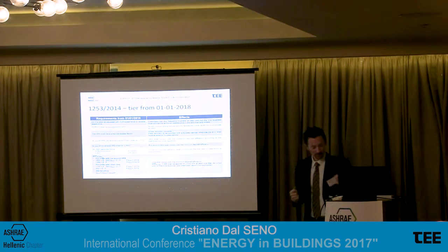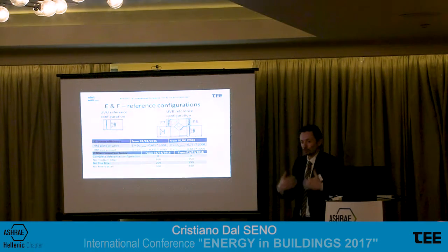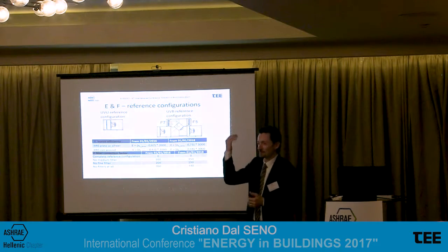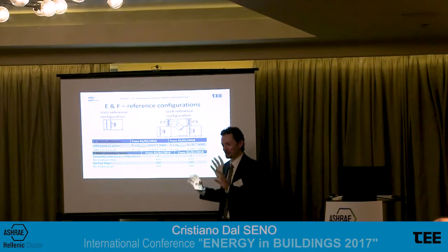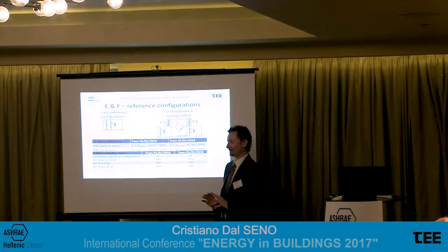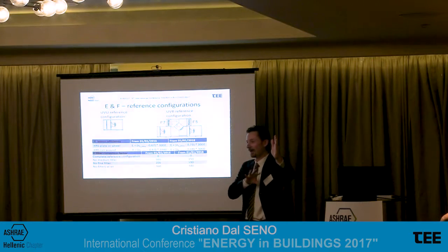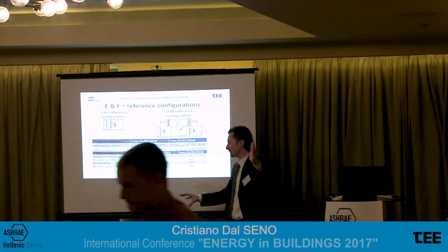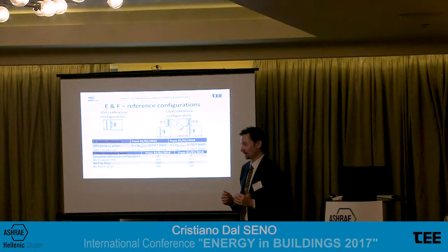Okay? Then somebody said, okay, pressure drops in the ducts are fixed, I should reduce the pressure drops inside the unit. Cancel all the filters, and the problem is solved. So, knowing that some producers are Italian, in the European Commission they said, no, pay attention. Filters should stay inside the handling units when calculating the pressure drops. Because we cannot look for very good efficiency and then create not comfortable situations inside the buildings. So removing the filters in order to decrease the pressure drop inside an air handling unit is not the way.